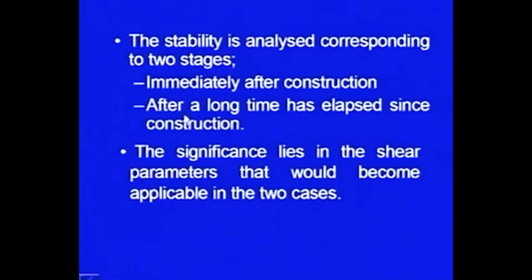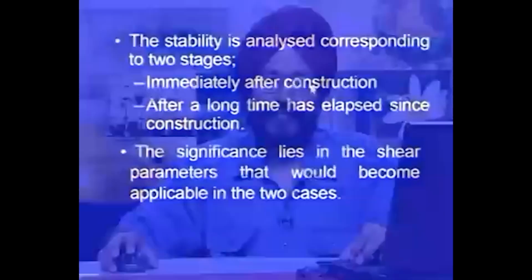What is the difference between these two? Immediately after the construction, the excess pore water pressure may be there. The excess pore water pressure may take time, it may take years to dissipate. There are certain soils in which the excess pore water pressure may dissipate very quickly.